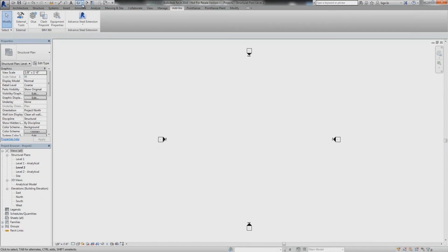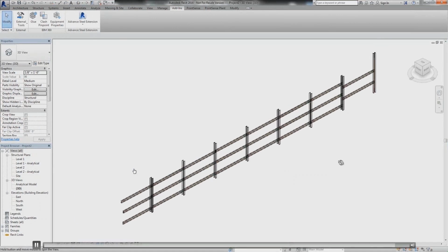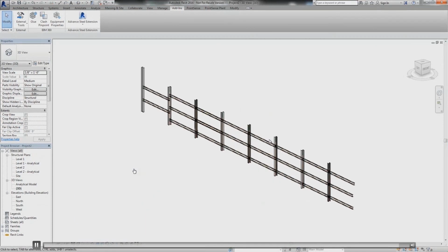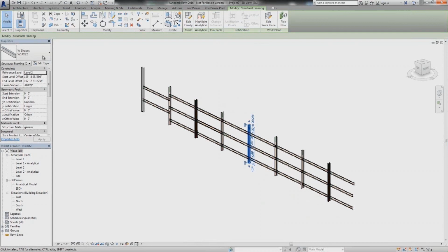So when you install that Revit MEP utility, you get this extra ribbon inside of your Revit, and all it's going to have on that ribbon right now for PointSense Plant is an option for extracting your MEP specs out of Revit, and then, when you're finished with your piping in PointSense Plant, an option to import the pipes back into Revit, and that way they come in with intelligence.